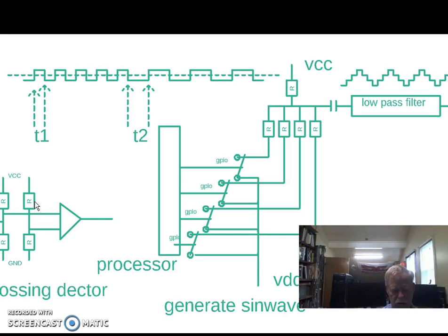So how do you pick up the zero crossings? One way you might do it is with a comparator. This is a comparator, and when this input gets larger than this input, the output changes, and conversely, when it's less, it changes back. So you can use this little analog circuit to generate flags when the signal crosses zero. There are lots of ways to do it, and this is one of the most prevalent, but there are other ways.